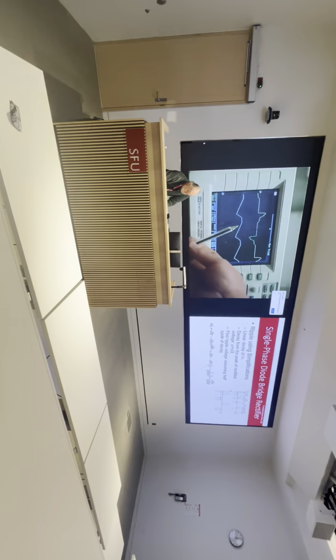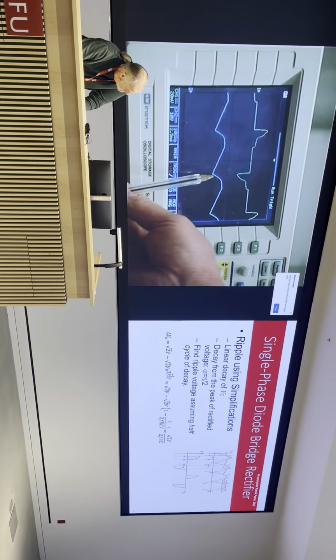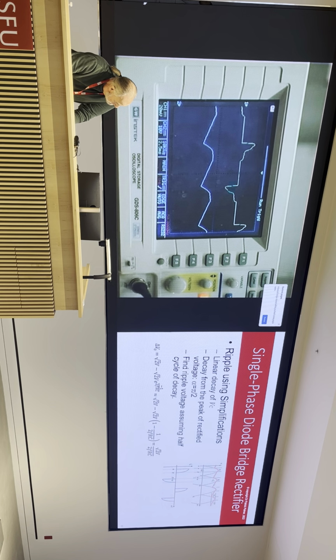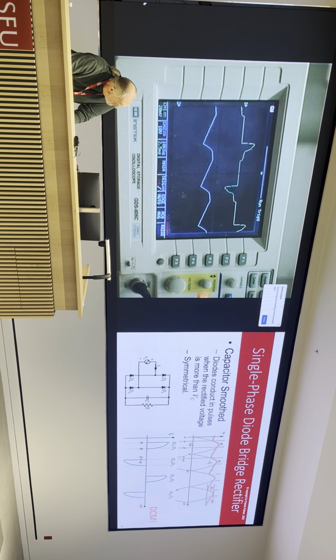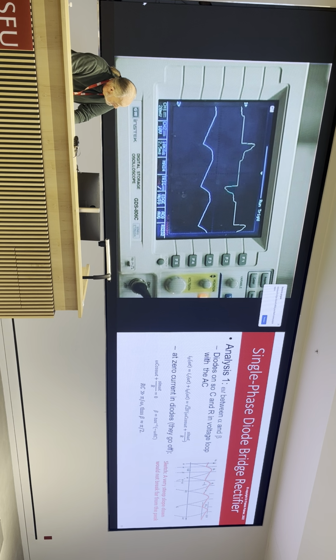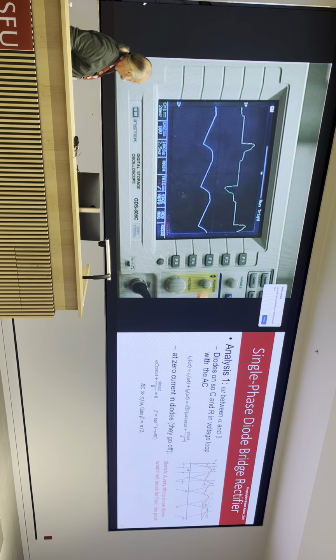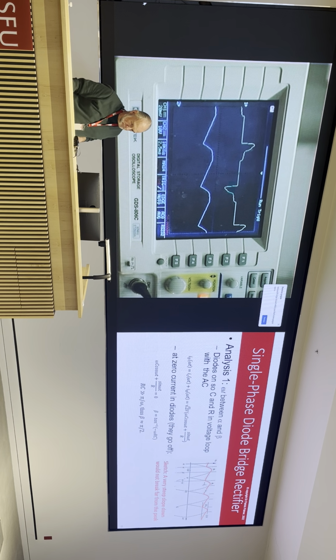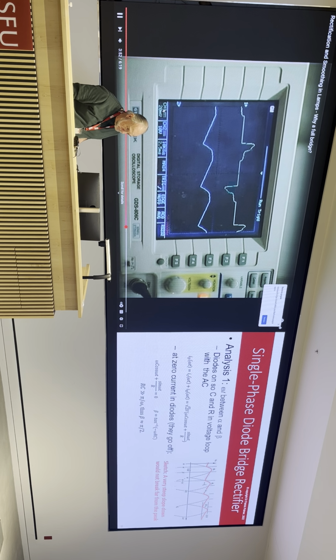The smoothing is reasonably okay, but it does have a big ripple on it. But from the point of view of our light, you'll see the light is very smooth. There doesn't seem to be any ripple in the light output. So we can say that this is smooth effectively enough. So this is part one of our compact fluorescent circuit. In the second part we will look at how the rest of the circuit produces the light.